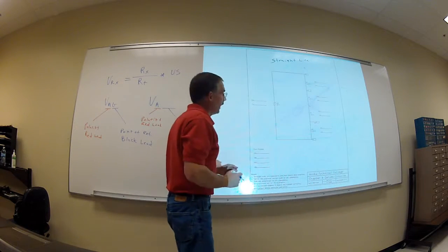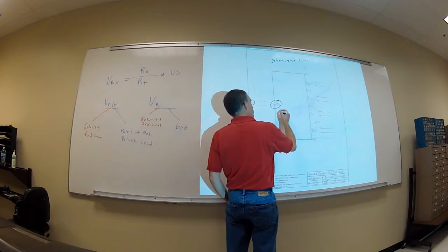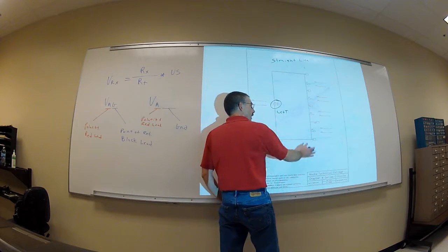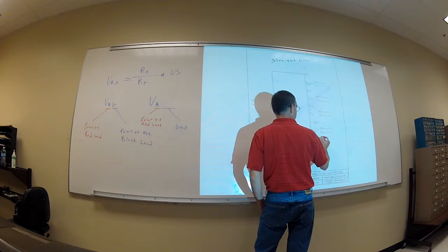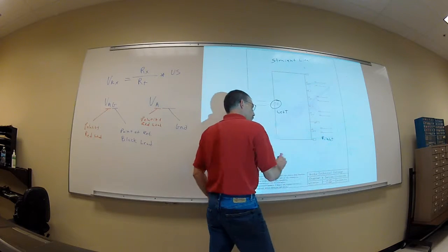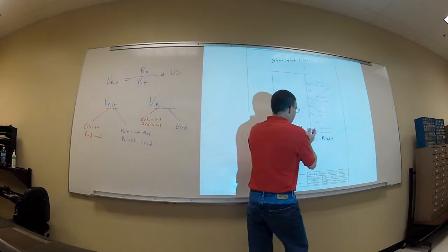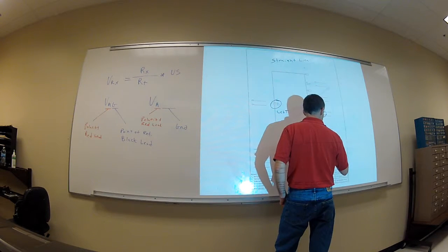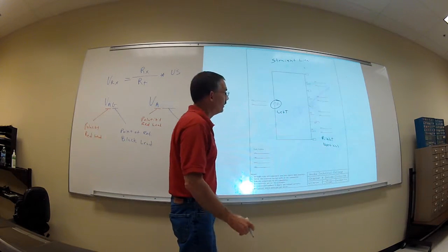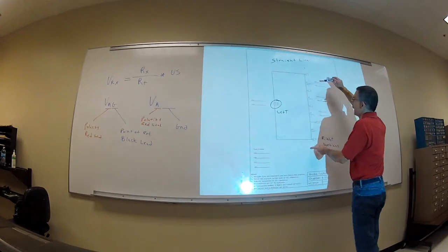And when we say straight line, typically we put our power supply on the left-hand side, and then all our components on the right-hand side. So we just redraw our schematics as we're trying to analyze them, so all our components are on the right-hand side, and they're all vertical. And it makes it a lot easier to troubleshoot than to have components scattered out all over the place.